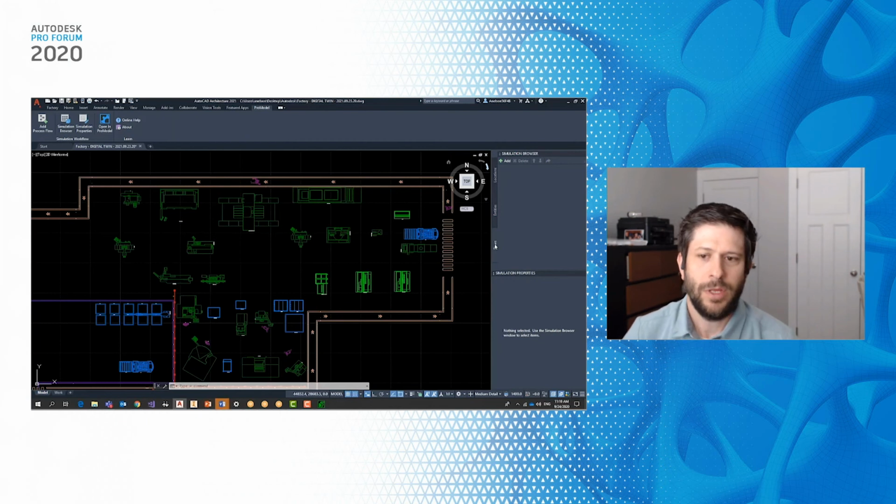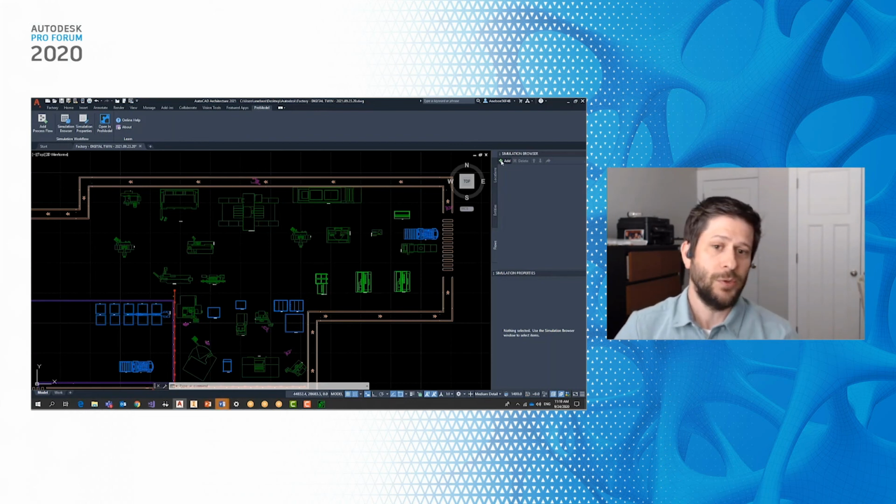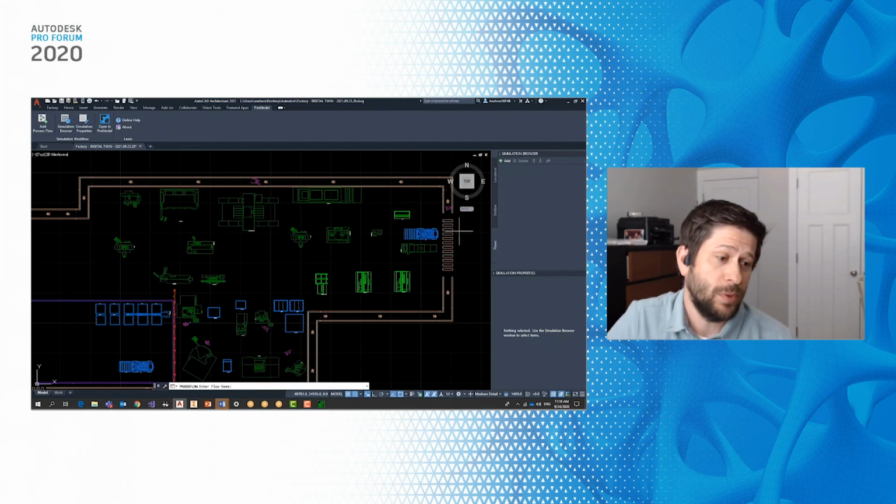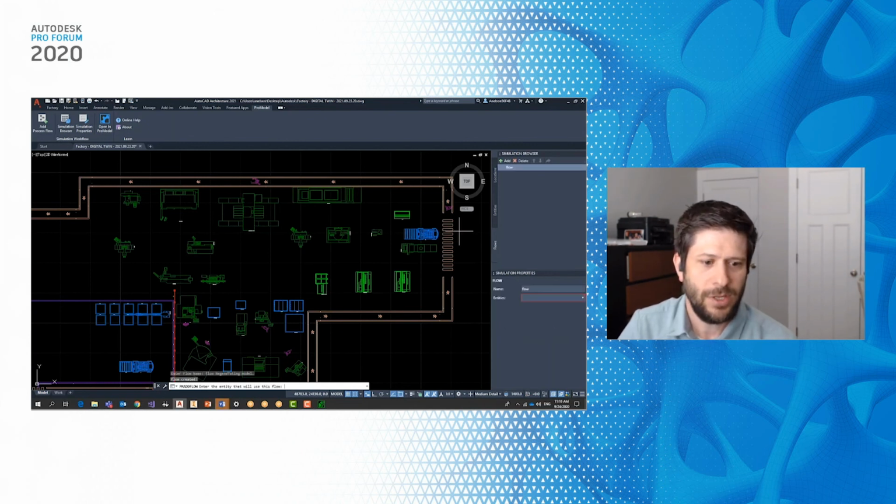But really one of the features that I like the most is being able to create a product flow. A product flow is basically how we did it in Process Simulator. We have a flow from location to location and what's moving from location to location. So you can have multiple flows in the ProModel Autodesk Edition. And each of those flows could have multiple entities if you like as well. So I'm going to select Add to add a flow. And down at the bottom in the command line, it says enter a flow name. So I'm just going to call this Flow 1.